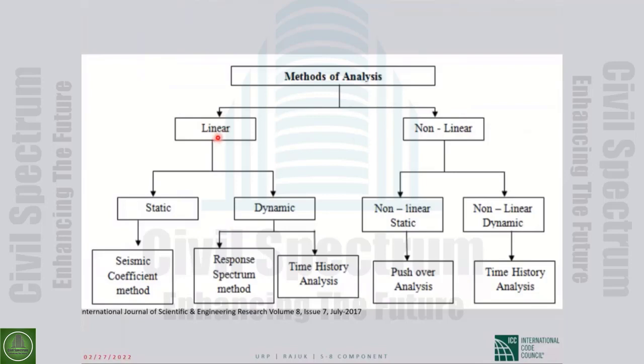The terminology we usually use is linear approach or nonlinear approach, and the criterion that usually is important for choosing linear or nonlinear is the level of irregularity in strength. Later we will see different measures, but generally, in a general sense, it is the strength. If the strength in the building is distributed irregularly, it's better to use nonlinear.